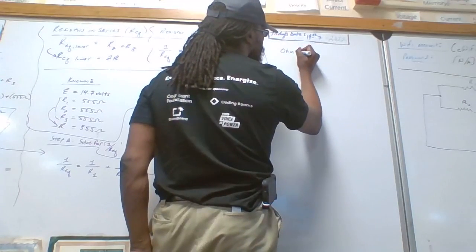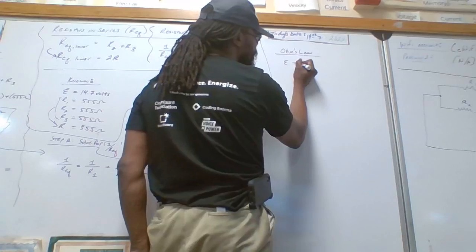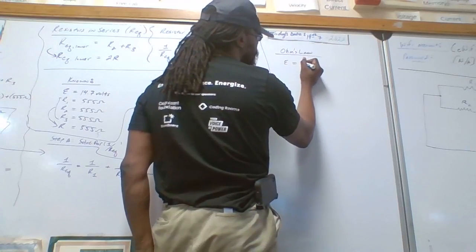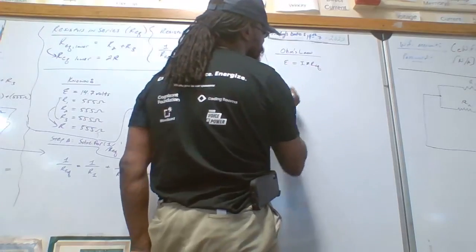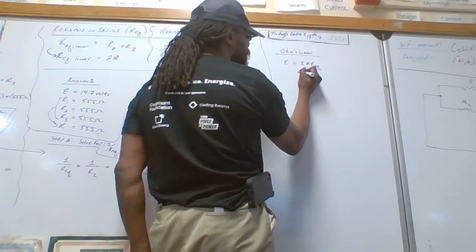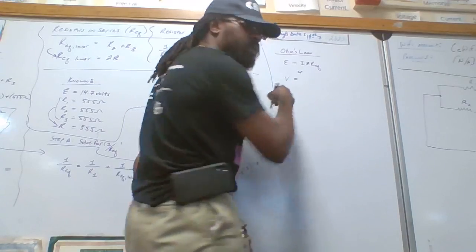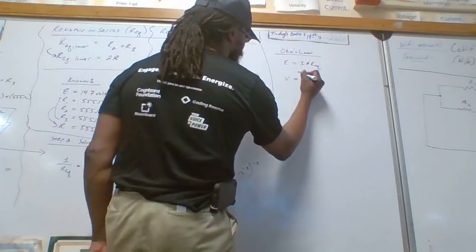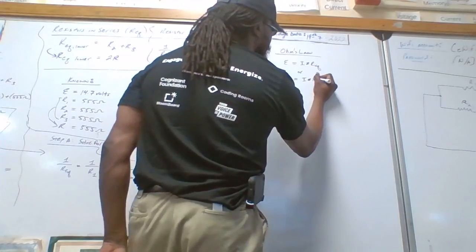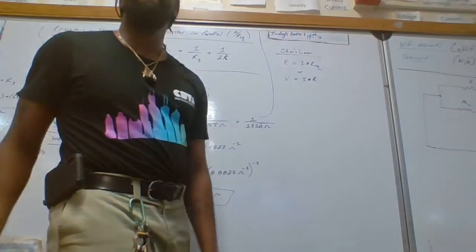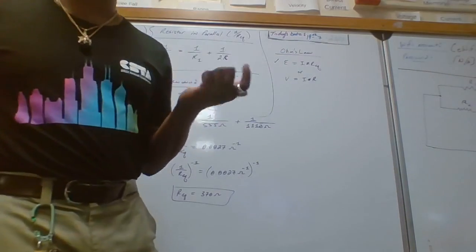So Ohm's Law can be written as epsilon, or EMF, is equal to the current multiplied by the equivalent resistance, which we're going to use. But another derivative of it is, if you didn't notice, V is equal to, you have potential difference as opposed to electromotive force. You have voltage is equal to the current multiplied by just the basic resistance. Okay. So we're going to use this one here to find our current in the system.